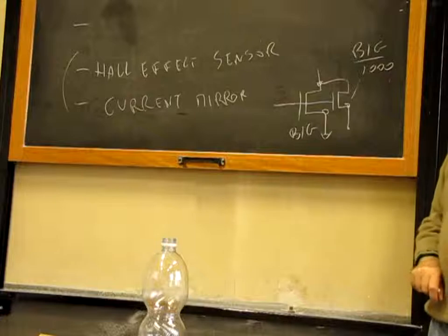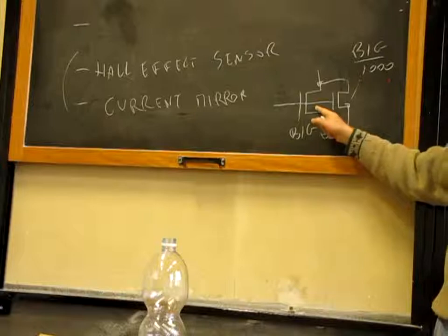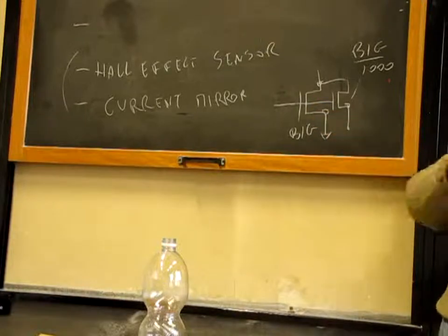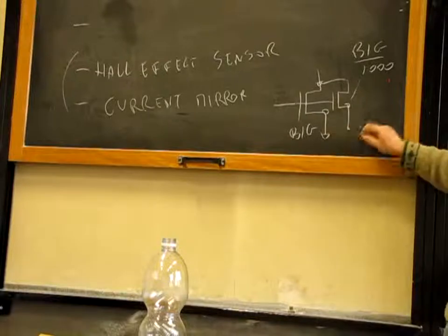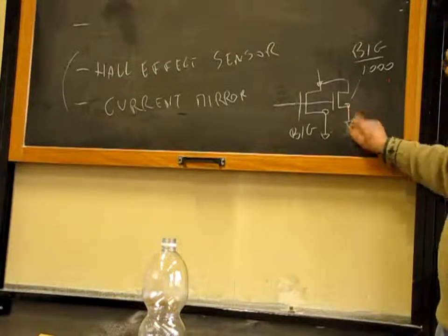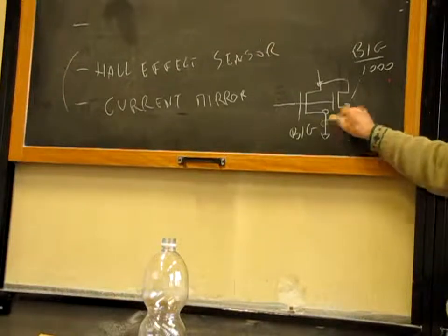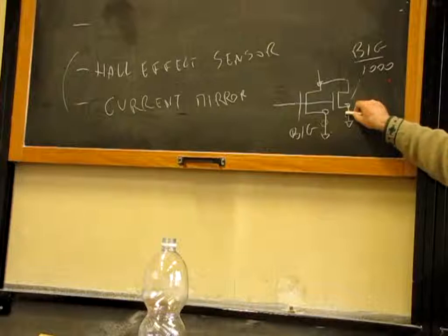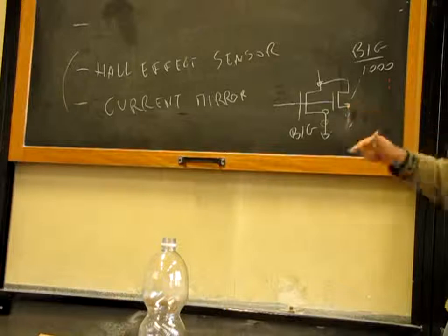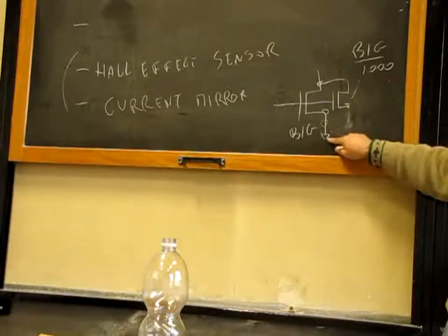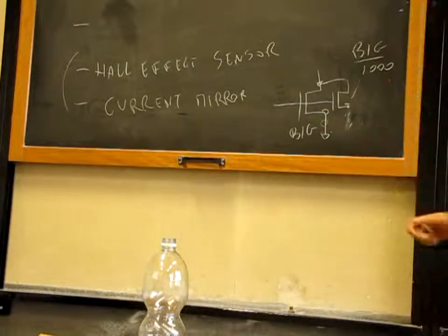And it was very easy, because in a silicon die you have many cells forming this transistor, and you just pick one cell and you don't connect its source with the other ones. If you put the two sources at the same voltage, this is important, the current over here is 1000 times the current over here. But then you still have to measure this current, and to keep the source at ground, because if this source is not at the same voltage as this source, the current sharing does not work according to the ratio of the areas.